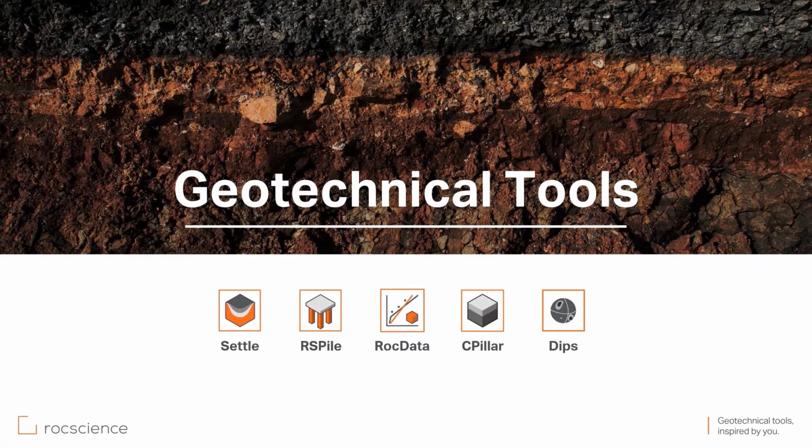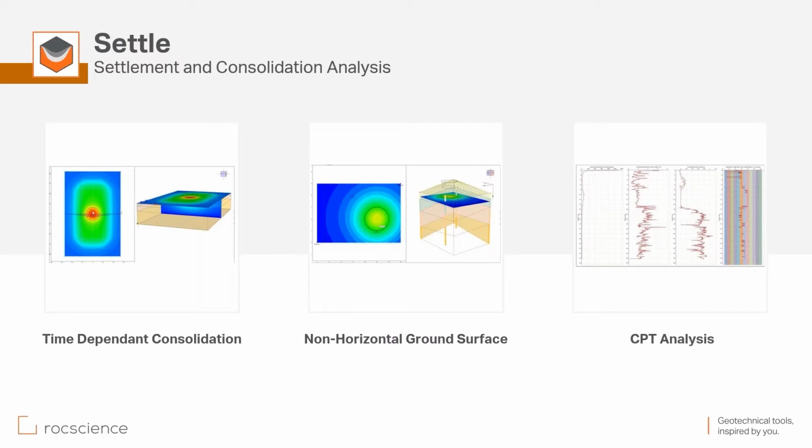And besides the first two sets of tools that I mentioned, we have another set we call geotechnical tools. These include Settle 3D. This is settlement and consolidation analysis. The basic formulation behind it is the Terzaghi consolidation theory. You can have time-dependent consolidation. You can define your model using non-horizontal ground surfaces and fully 3D geometry, and we have a powerful CPT module in it to do CPT analysis and also